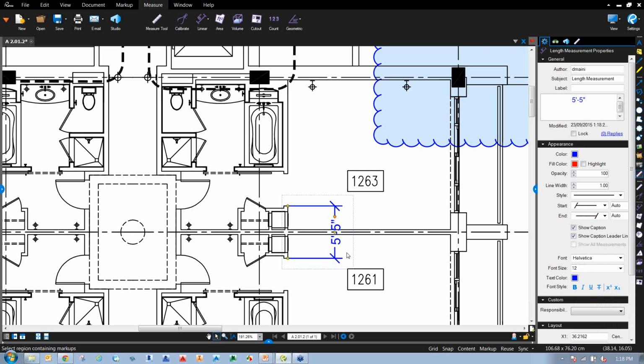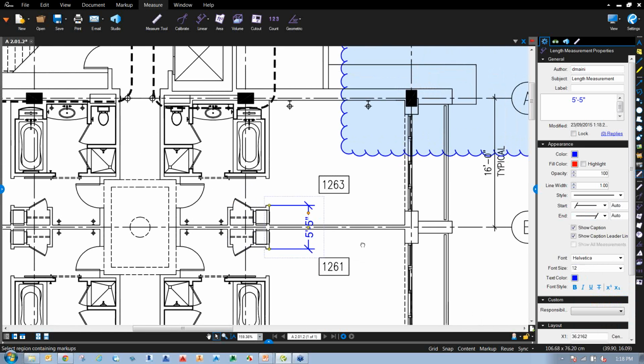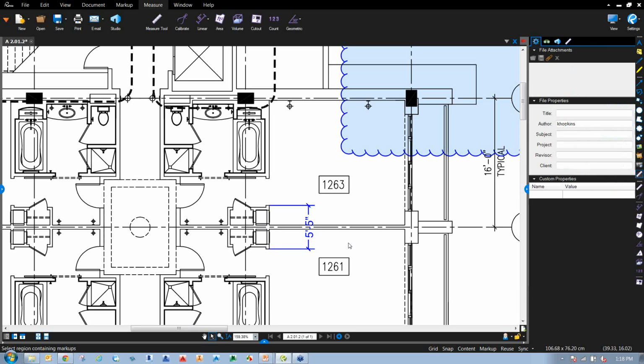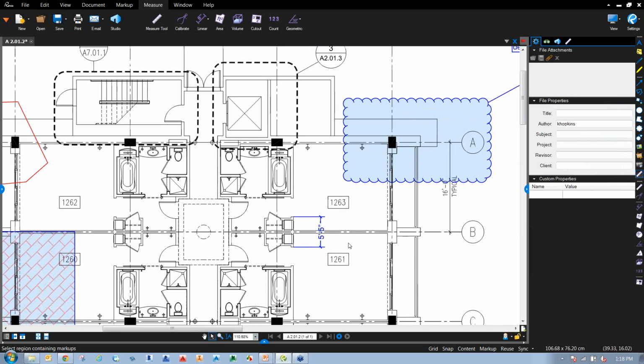The problem with this architectural text is that this actually is pretty large size compared to the rest of the architectural text. So I can go in here if I just drag it out a bit. So under this little list here, I can also go and change the size. I'm going to make it 50% and make this 50% as well. So this is how I want my dimensions to look like.